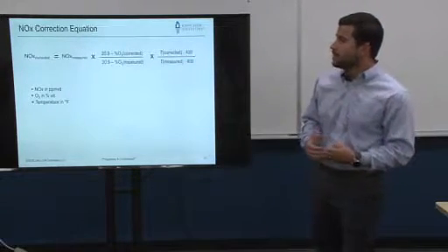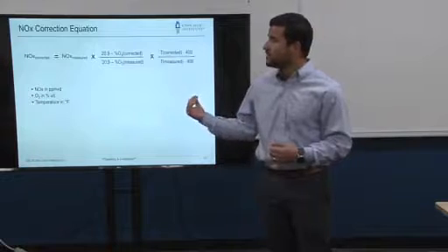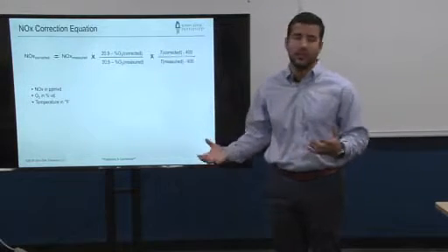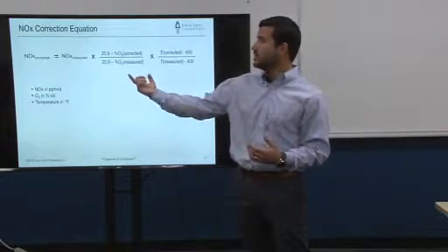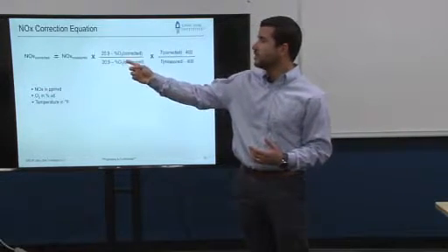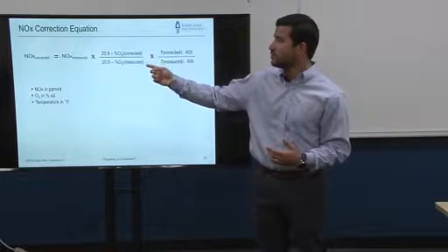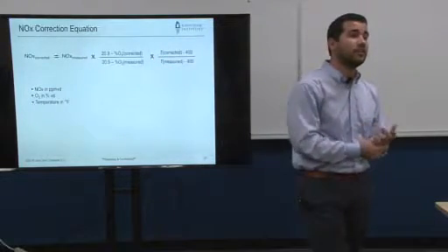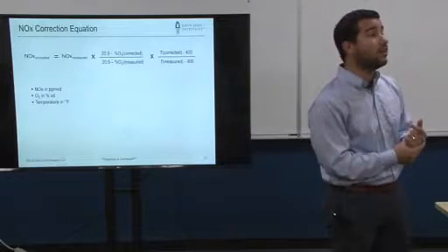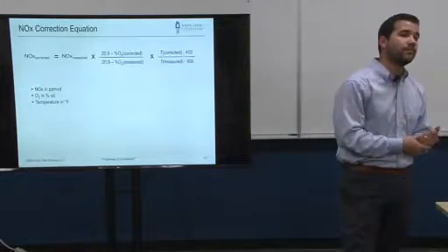Okay? So the first term on the right side of that equation is going to be obviously the NOx you measure in parts per million. And then all you're doing here is just a volumetric correction. You take the 3% that you correct to versus what you measure. And that's going to give you the factor for the NOx that you're going to be reporting.